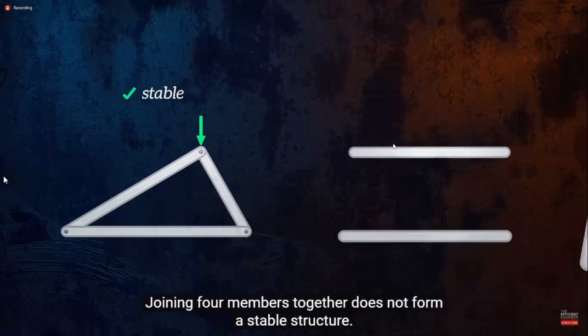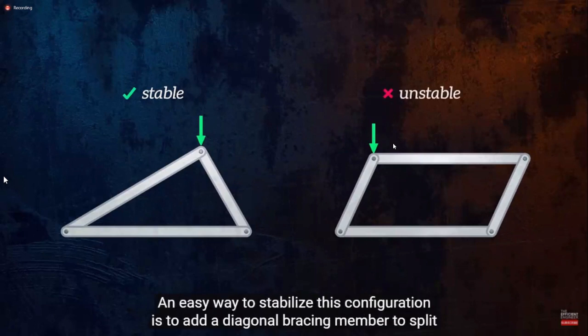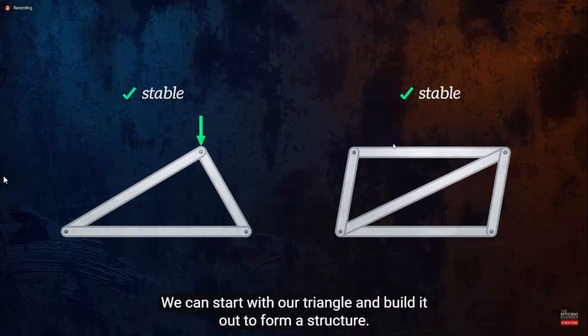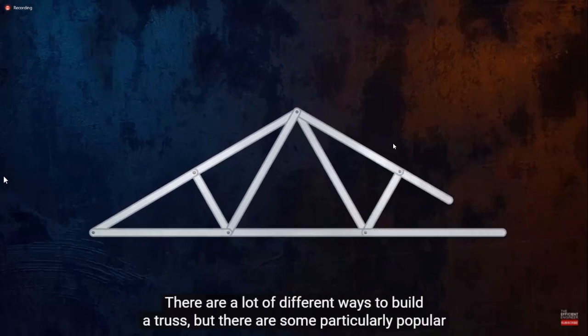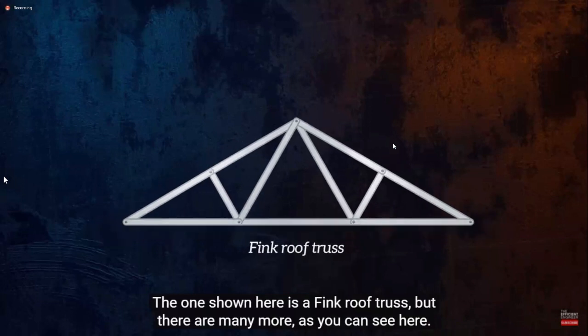Joining 4 members together does not form a stable structure. The angles between members can change without any change in the length of the members, and so using a 4-sided shape as the base for building a truss would be a terrible choice. An easy way to stabilize this configuration is to add a diagonal bracing member to split it into triangles. We can start with our triangle and build it out to form a structure. There are a lot of different ways to build a truss, but there are some particularly popular truss designs that you will see again and again, and so they are referred to by specific names. The one shown here is a Fink roof truss, but there are many more, as you can see here.